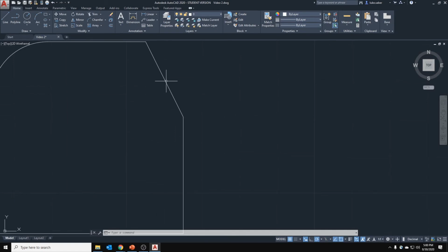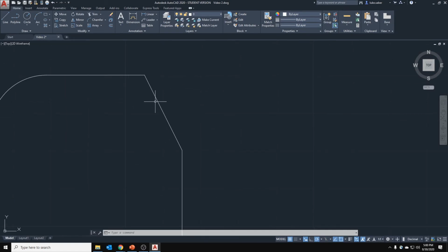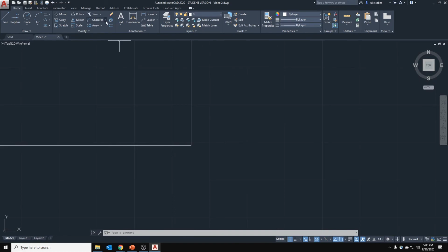So that'll make this kind here. But let's say we wanted to make something a bit different. We could do it with an angle. So we could do chamfer, right click, angle. It'll say the first length, we'll make that 0.5. And then we'll right click to enter, because you can do enter or right click most of the time. And the chamfer angle from this first line here. So it's going to go here and then out. So let's say maybe 40 degrees. Why not? Right click. This is the first line, and here.